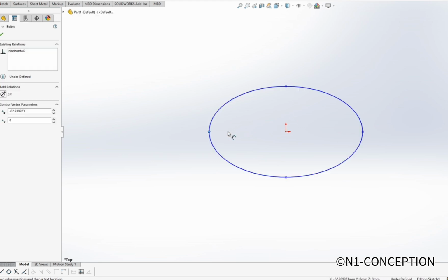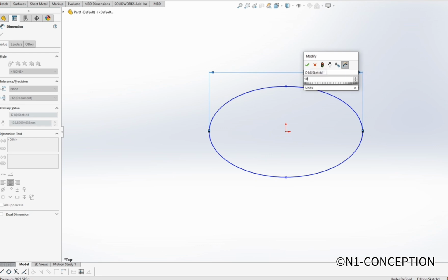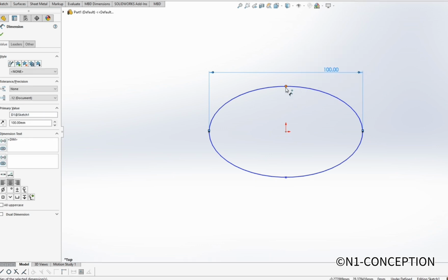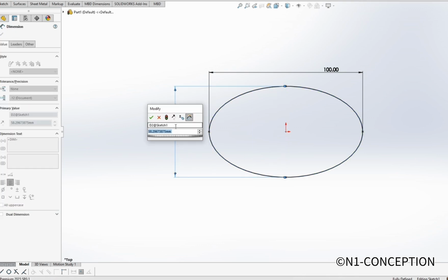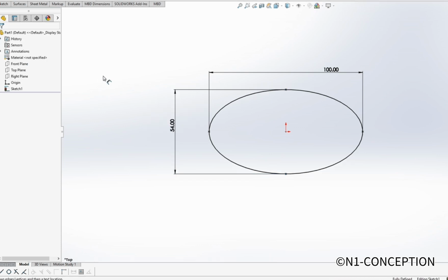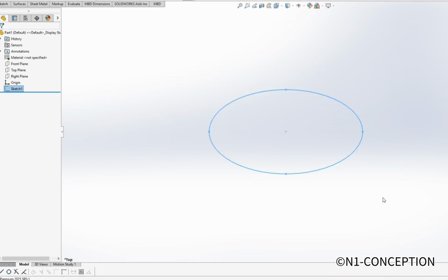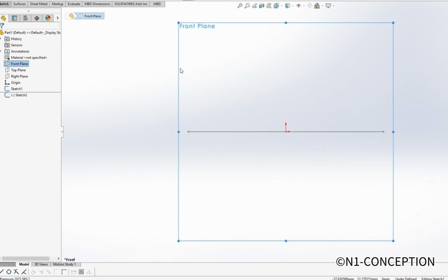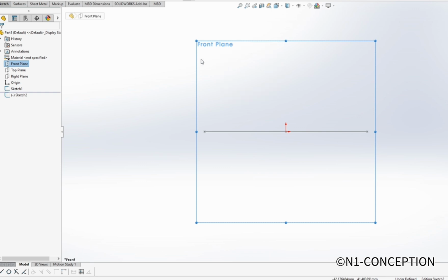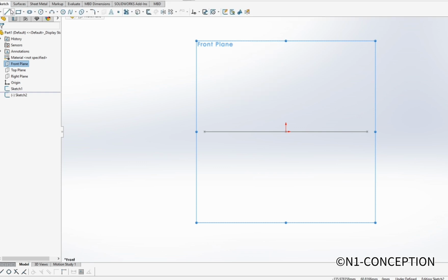To begin with, I started on the top plane in SolidWorks. The basic idea was to first capture the iconic wavy curve of the chip. Unlike a flat object, a Lay's chip has a slight saddle-like surface. To replicate that, I sketched out a simple curved ellipse profile using the ellipse tool, and sketch length was around 100 and thickness is 54, all dimensions in MMGS. Then I exited the sketch. This gave me the base outline of how the chip would bend and twist in 3D space.